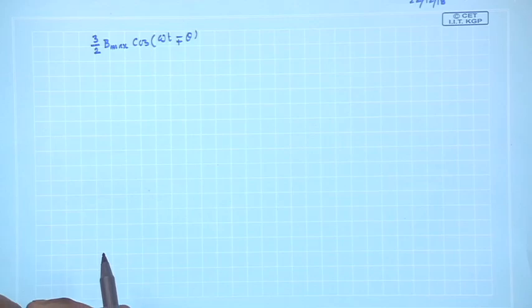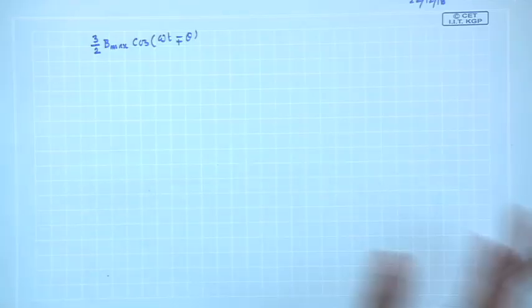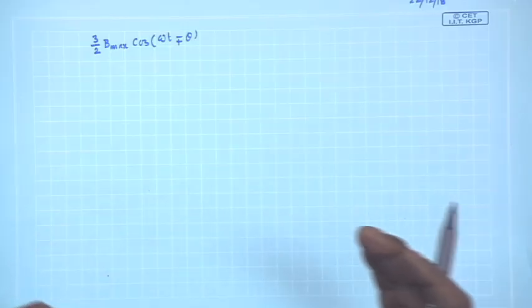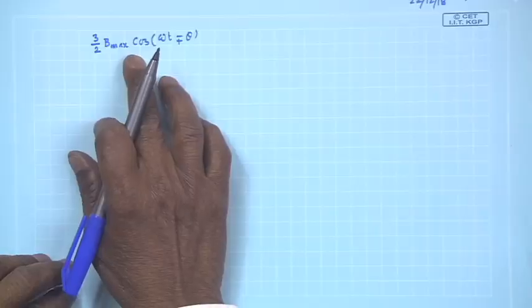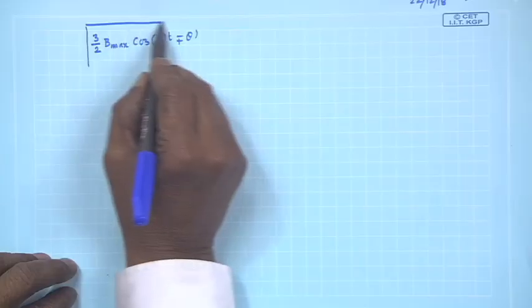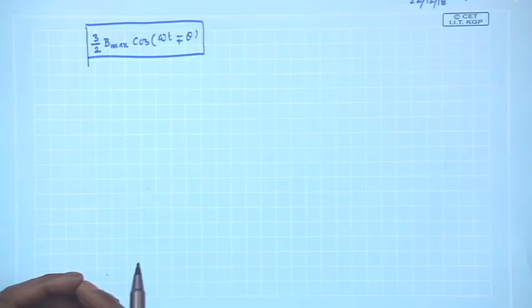If you take the minus sign, it indicates a field moving in the forward direction of theta, and if you take the plus sign, it indicates a field moving in the negative direction of theta. This is a standard equation for a travelling field. We will examine that in great detail, and also show you from another point of view how this rotating magnetic field really moves as time passes.